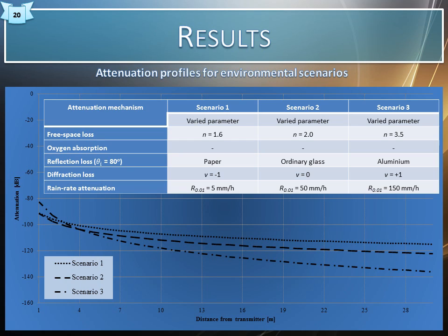The attenuation at small distances from these results suggests expected attenuation of approximately minus 100 dB for the three scenarios, and these results are used to determine the required order and feasibility of a passive low-pass filter to accomplish similar attenuation at millimeter wave.